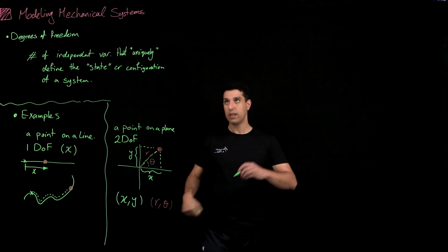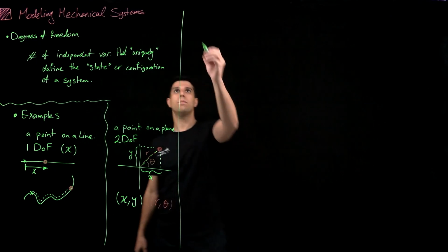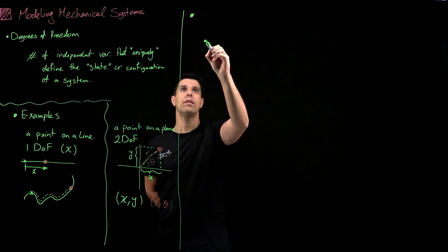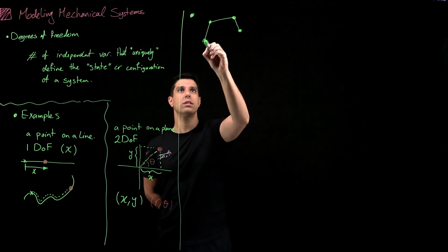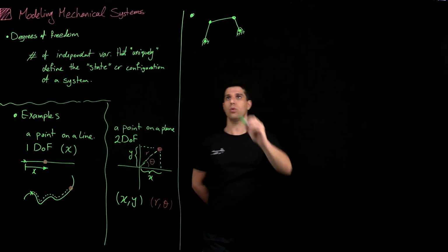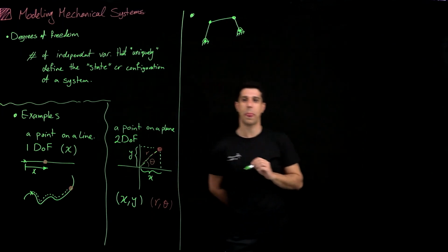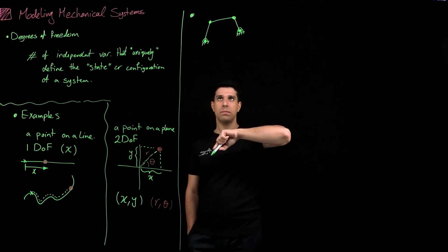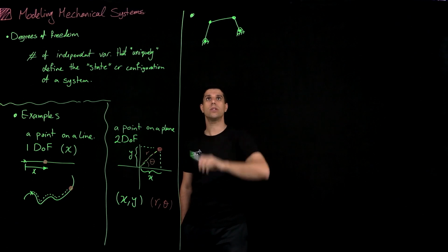All right. So maybe as the last example, another example, final example. Imagine now I have a linkage. This is a famous linkage called a 4-bar mechanism. These 2 points are fixed to the ground, and these are just pin joints that the links can rotate freely about those.